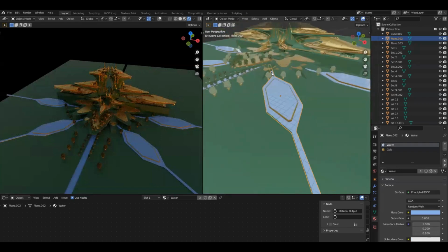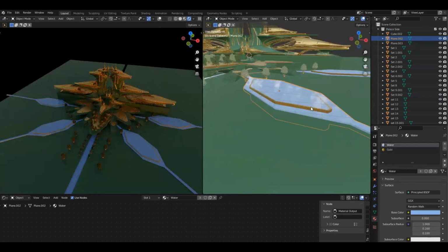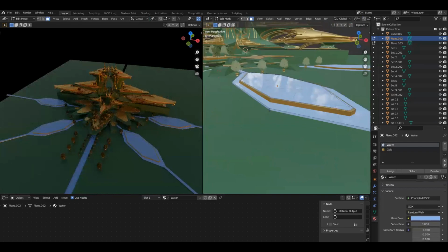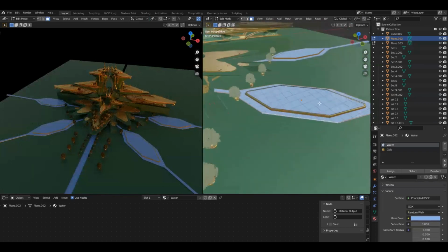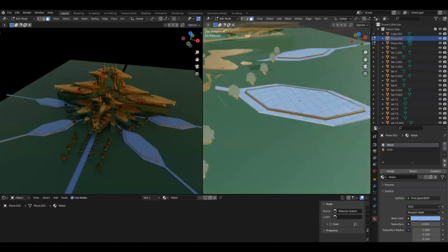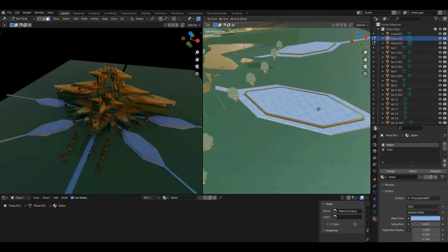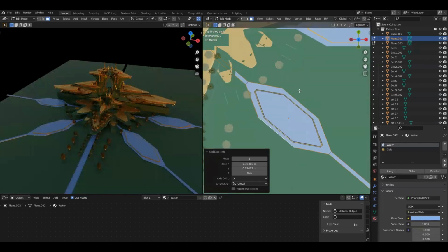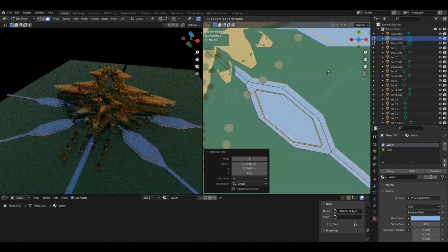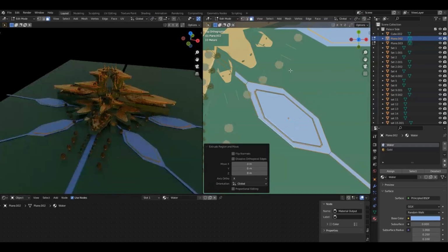And then I think we will need a little bit of an edge trim as well. So let's go back into edit mode and let's see what happens if we alt click the faces. We should select all the edges all the way around. And in this case, I am going to shift D to duplicate that and click to place it. And then that's just to kind of separate it from that mesh. And then we'll extrude that. We'll extrude it, but then we'll hit escape to cancel the movement of the extrusion, but it's still extruded.